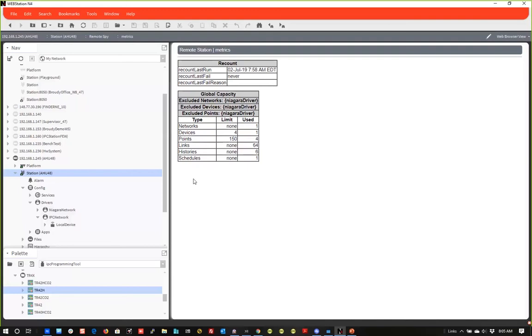If we're going to be using those with the panel bus, then at some point you would think they would allow it. You should tell them that this is a full Jace in a supervisor. Yeah, it's a good point. Right now, if you were to bring this into a supervisor, because you really wouldn't bring it into a Jace since it's a Jace in itself, it is going to count as a Niagara device on the license of your supervisor.